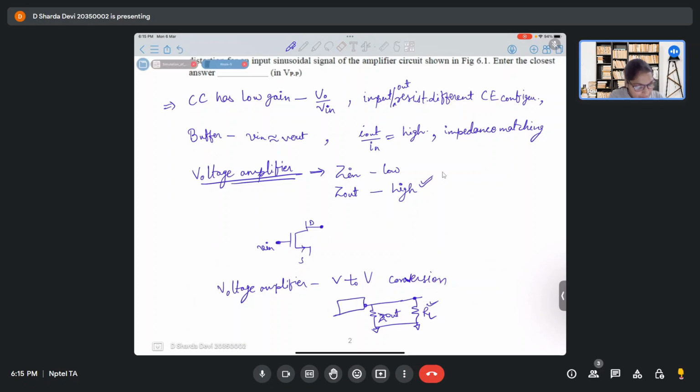Let's say here it is the amplifier. Yes, there is an amplifier and this Z out is like this, and there is this RL, right? So in this type of configuration, see why I have put my Z out in series? Ma'am, the voltage will be divided.